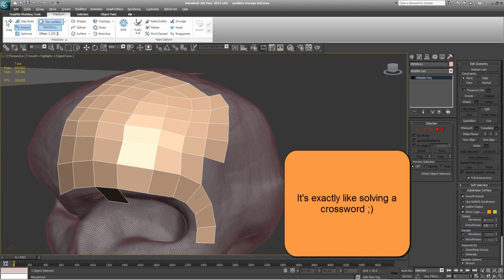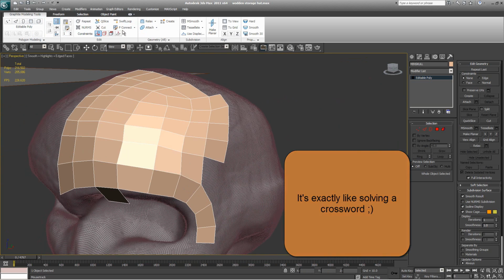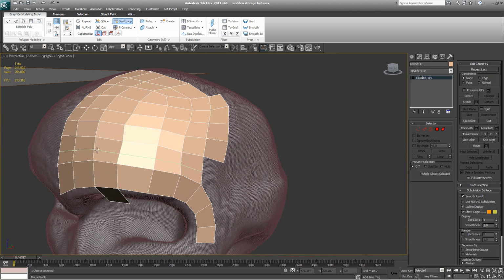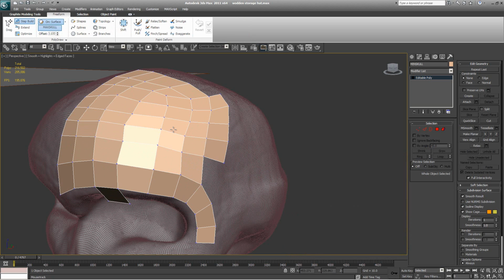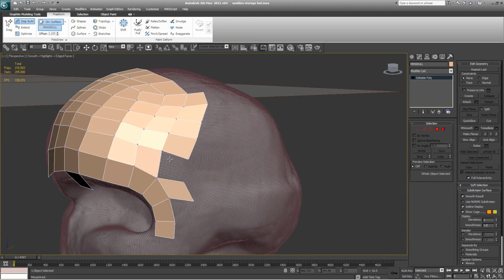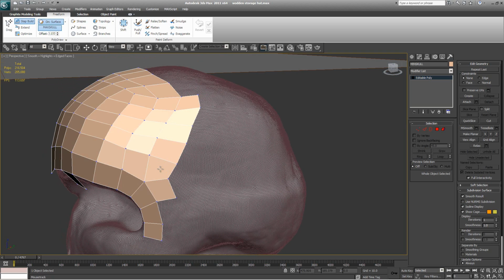And for example over here, you don't need to create an extra swift loop over here, although you could, and then have this bottom polygon going down like so, and then this polygon going out like that. Instead, you can actually go into the freeform, go into step build, and lay down two vertices over here, create a polygon here, and create another polygon there, instead of doing that. Put two vertices here, lay down a polygon, lay down another one, and suddenly you have another loop which goes over there. And this one isn't triangular and isn't a pentagon, it's just a quad, and a very nice looking quad.